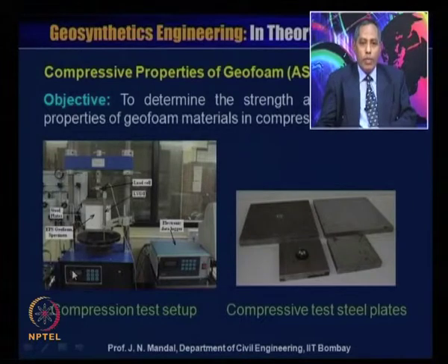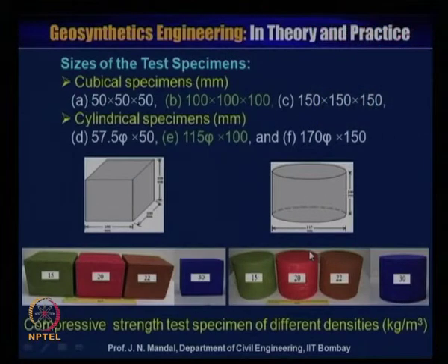You have to place the compression test steel plate at the bottom and the top of the expanded polystyrene geofoam material to apply the load uniformly.